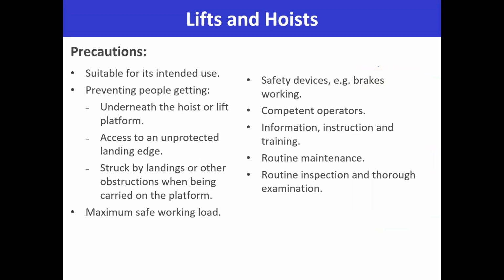Okay, what are the precautions for lifts and hoists? You need to provide a suitable lift and hoist for the intended use. Prevent people getting underneath the hoist. Never ever allow people to stand underneath the hoist or walk underneath the hoist, because the load or the hoist can fail at any time and it will fall on them.